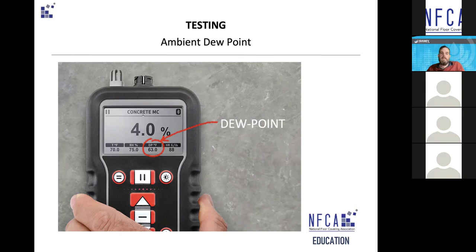And correcting ambient humidity is easy. The whole water damage industry is based on it. They rent out air movers really easily from places like Sunbelt and others. They'll deliver them to site, air movement, dehumidification, whatever is needed. The important thing is to know what you're doing. Don't just try to dry something out, because too much heat, too much dehumidification, too much air movement can cause problems.